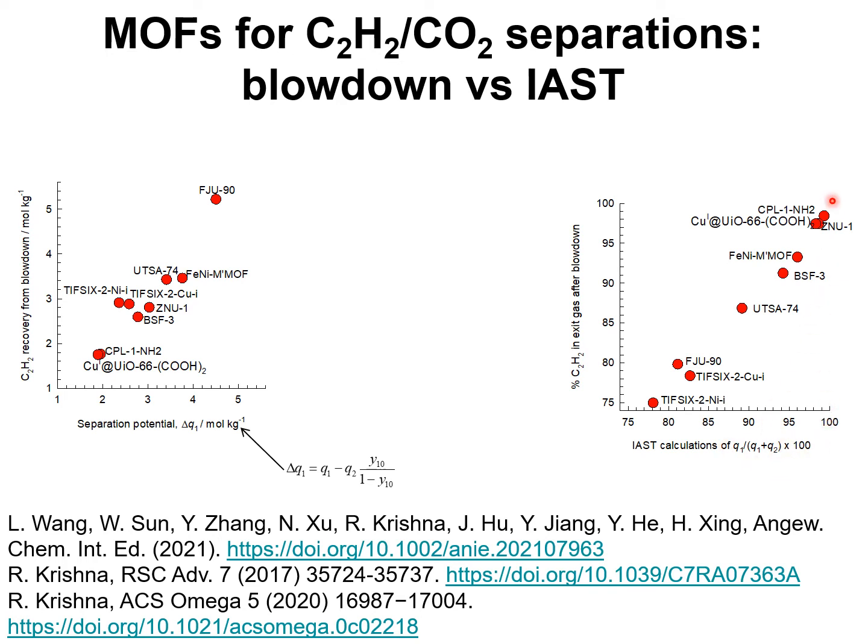So you can see that there is a practically linear relationship between the IAST calculations of the product purity that is expected in vacuum blowdown and the actual purities that are realized in the blowdown simulations.